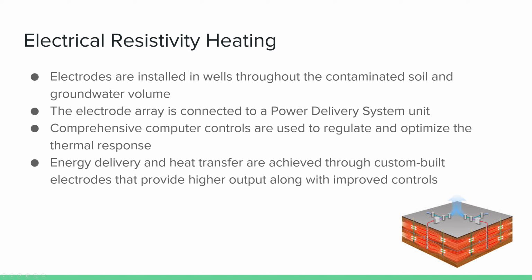Also, it is more effective at energy delivery and subsurface heating that is provided by real-time computerized power controls for each electrode separately. Convective energy delivery is available in permeable settings, making it possible to generate and inject steam for additional heating and contaminant flushing. Lastly, safety and process transparency are enhanced for both the project team and clients with real-time digital at the source temperature and monitoring. The electrodes are typically constructed of graphite, steel, and or electrically conductive material within a borehole.